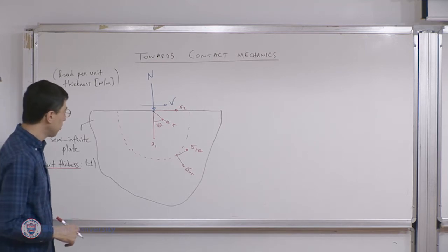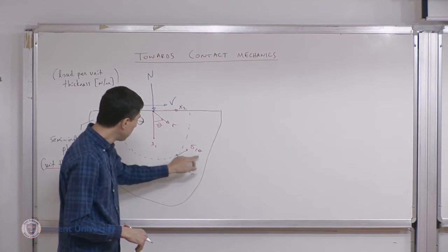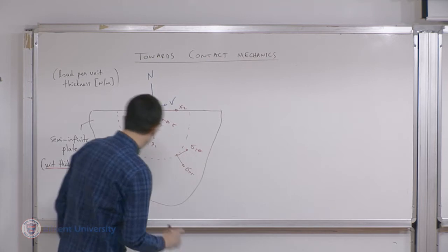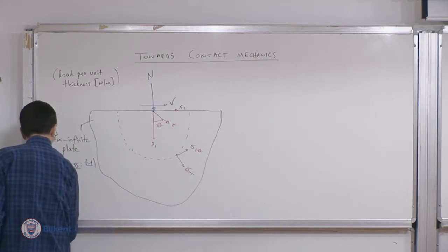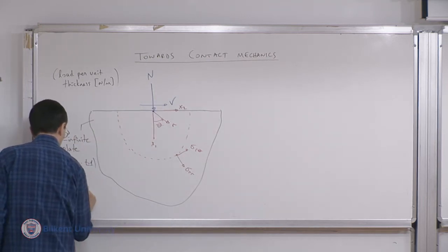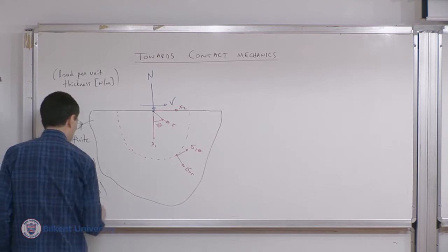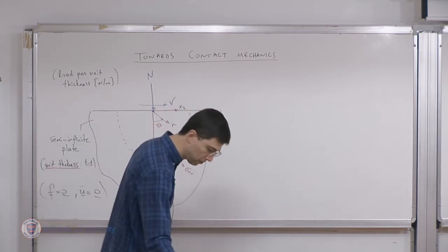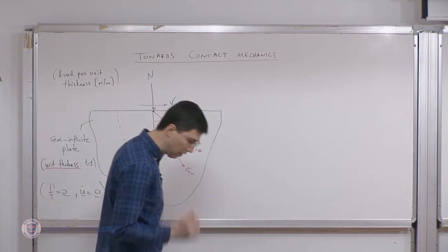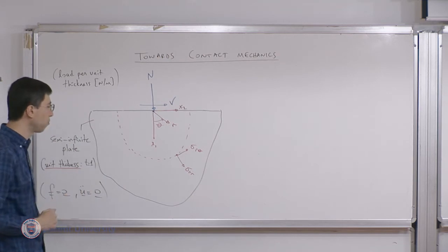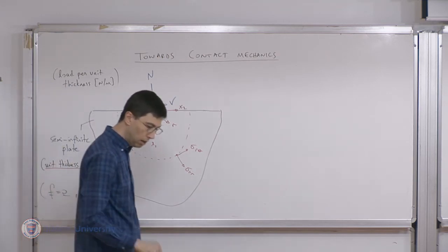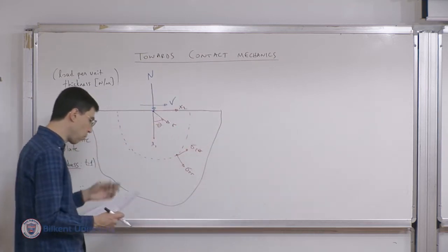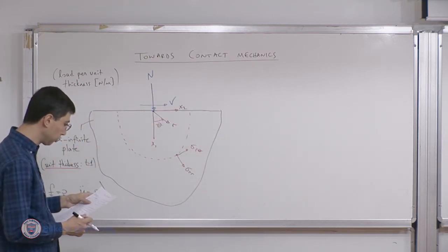Eventually, there is, of course, also a sigma theta theta, but I'm indicating these explicitly because shortly we will make use of it. So the conditions are that there is no body force and there is no acceleration. The only thing that we have is this point force on the semi-infinite plate of unit thickness. Again, our solution will eventually hold for plane stress or plane strain, but let's imagine that in practice we're aiming more for a plane strain type of condition.